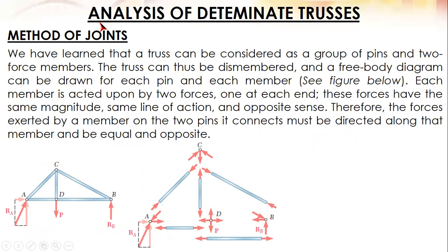So, the first method that we're going to use in analyzing determinate trusses is the method of joints. The method of joints is suitable if it is required to determine the force of all members. For selected members, then you will use another method.